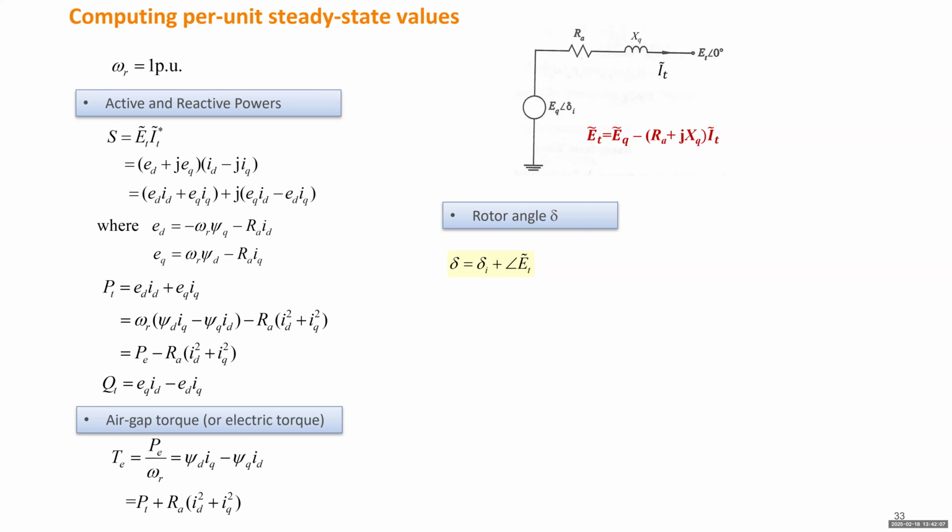It is related to the rotor angle. It is like some internal angle with this EMF, electromotive force. The actual rotor angle is really this angle. We have to define some reference. So if we use the terminal as a reference, if we assume the terminal is connected to a very large system, that large system doesn't oscillate, or that large system has a constant angle.